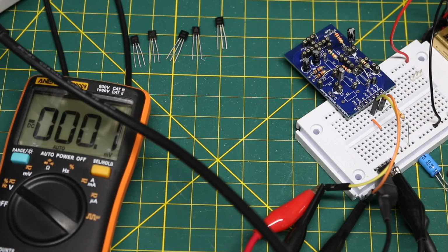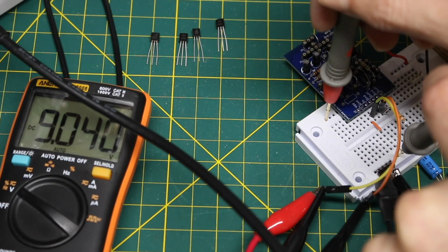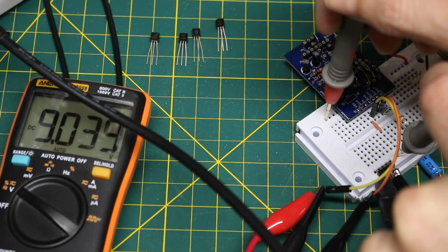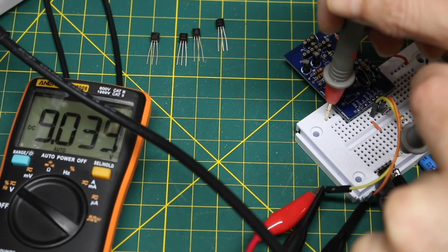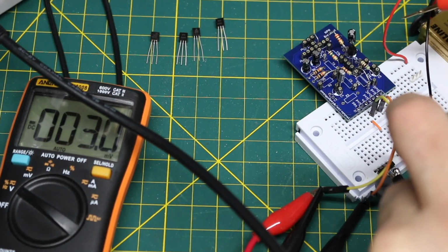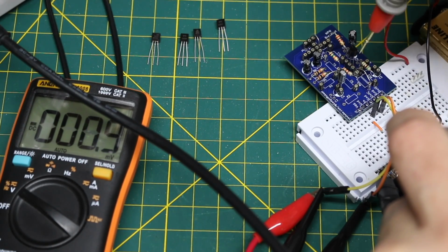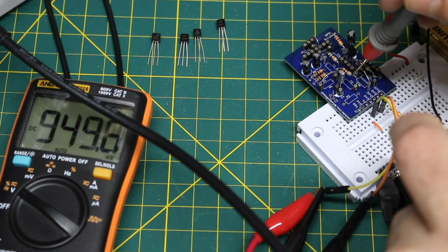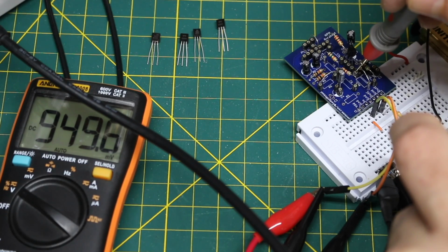I checked the other three, so we have a beta of 216, 433, and 216 again. So that's a 2N2222, 3904, and 2222. We have 9.04 volts or so as our power rail. Now, checking the voltages on the emitter, we basically have 950 millivolts with a calculated 1 volt expected, so that